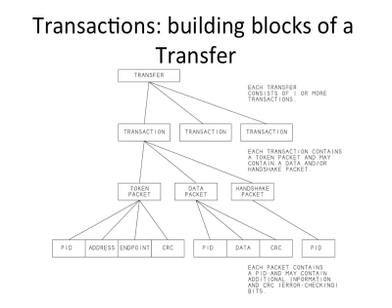Okay, so a transfer is made of multiple transactions, and a transaction is made of multiple packets, and these packets may contain the endpoint ID, the addresses, error checking code, or the actual data. So this is the logical structure of these different building elements of USB communication.